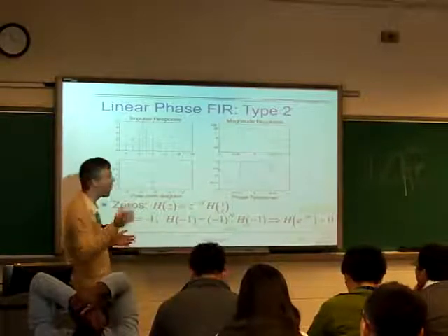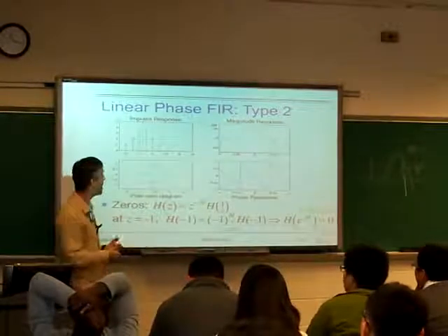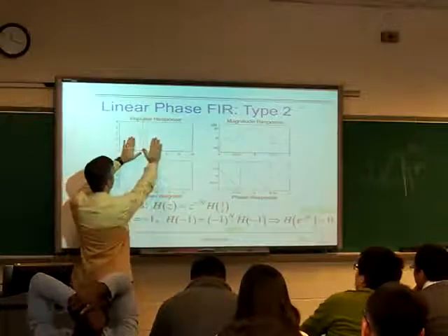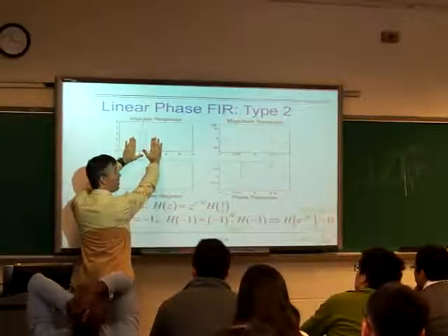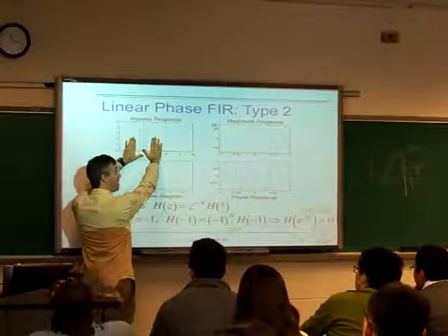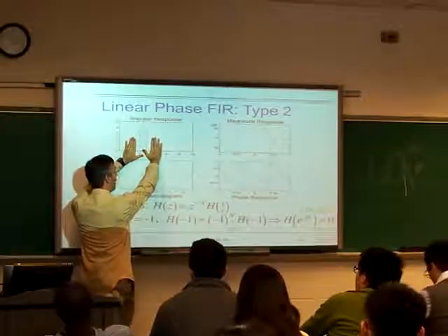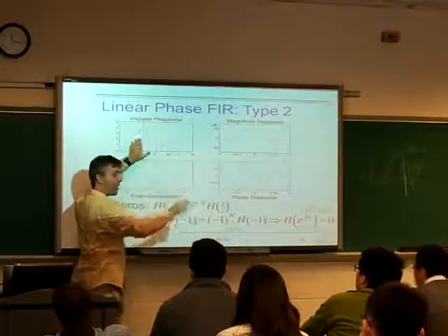Right? That's the highest frequency sinusoid we can represent without aliasing. And you can sort of see that. This is the most simple even length symmetric FIR filter. And it's just the summing of two adjacent points.